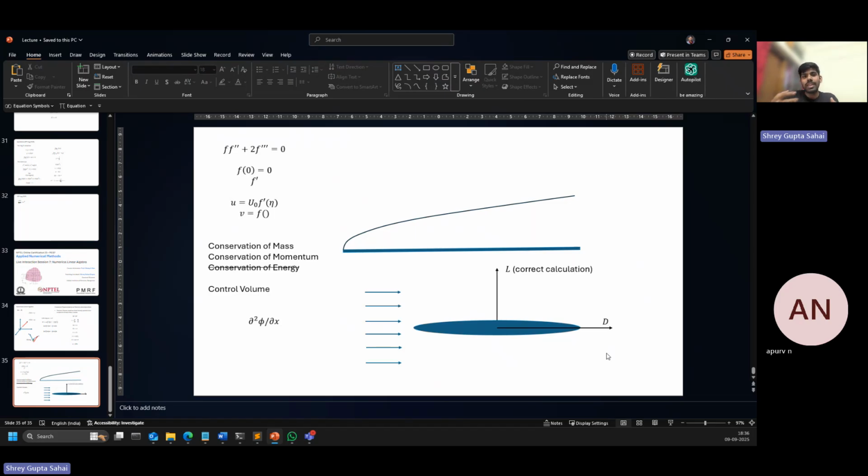Or is it also because of the pressure difference at the front of the bus, or some vehicle you're sitting in, the first face of the obstacle, there is high pressure. At the behind there will be a low pressure. Because of that there will be a drag. What do you think is the major cause of drag? Is this a pressure drag, a form drag kind of stuff we call, or is it a skin friction drag? What do you think?